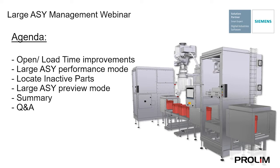We'll review how Solid Edge now allows us to interact with inactive parts inside of Assembly Model to reference, select, measure, and edit while parts are inactive. Large Assembly Preview Mode is another new tool to Solid Edge that allows us to open up very large assemblies in a limited mode for quick viewing and referencing. We will also briefly look at internal components to better assist us with those large assembly performance and management.